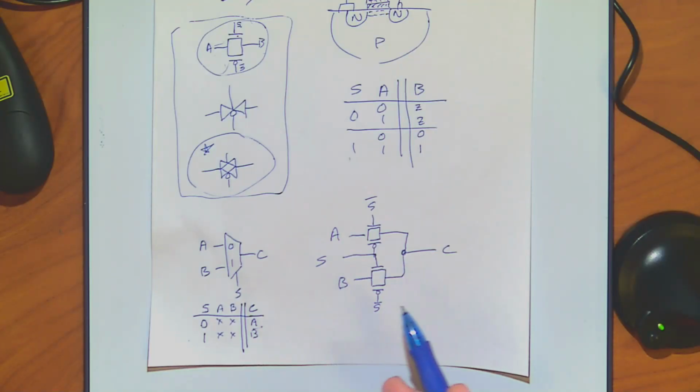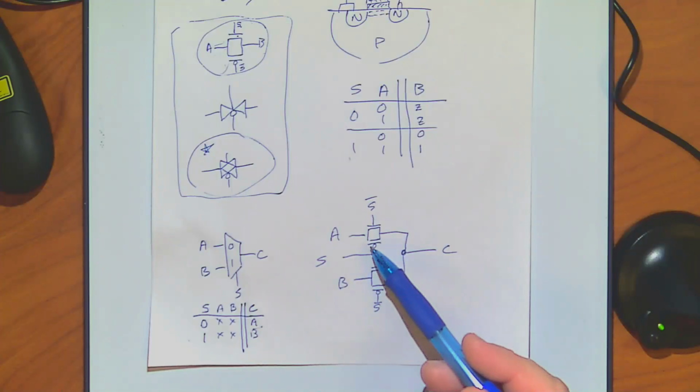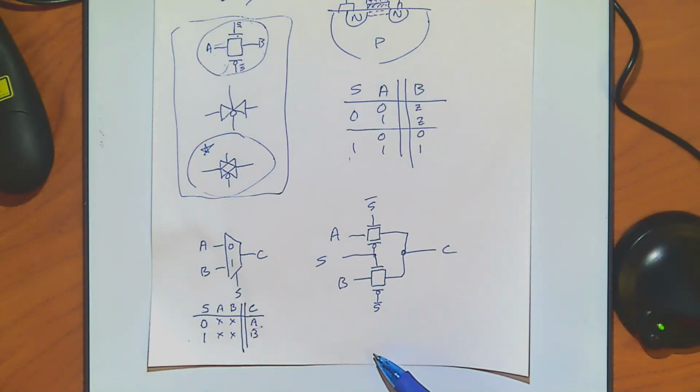So if I want to do 2 of these, I'll need 2 levels of the selection, and then another one to select between them. So I'll need 3 to get 2 levels of this setup. But that still means to handle 2 of them, I only need 12 transistors. Again, very, very efficient. It would be very hard to build something this efficient in some other logic form. So that's where this one kind of really shines.